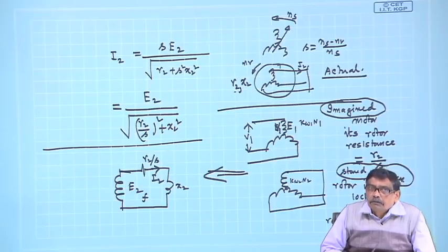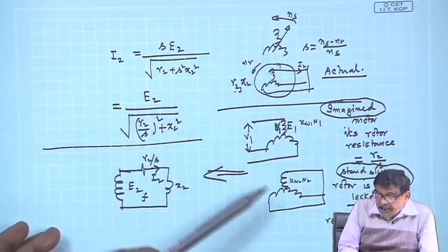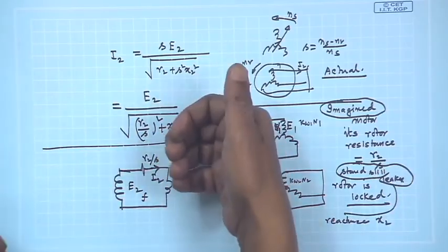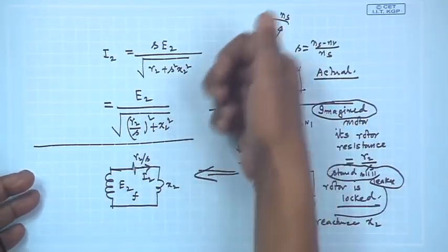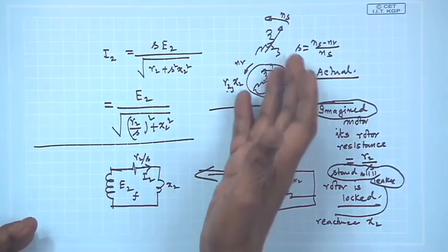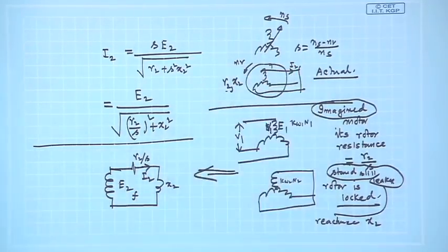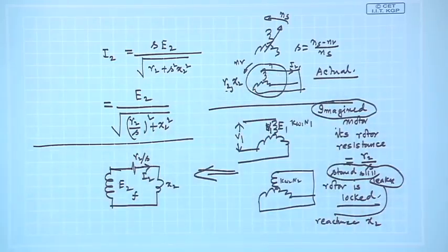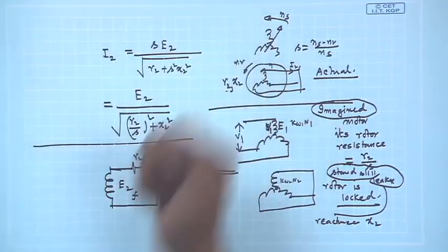Therefore, the stator should react in the same way, that is, draw the same additional current from the supply to balance the rotor MMF in both cases. There is no way the stator will ever know that the rotor was rotating at some slip S or some speed Nr, and that it has to draw an additional current.